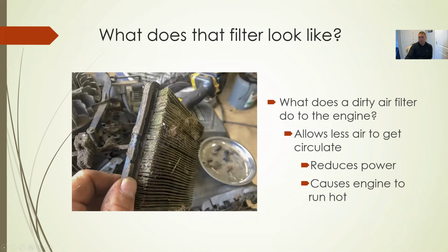Is that what that air filter looks like, right? The engine's trying to suck in air through that air filter. You're obviously not going to get very much clean air through there. So that engine's going to be under stress, right? So what does a dirty air filter do? It allows less air to circulate, which reduces the power and causes the engine to run hot, which, at the end of the day, shortens the lifespan of your equipment.